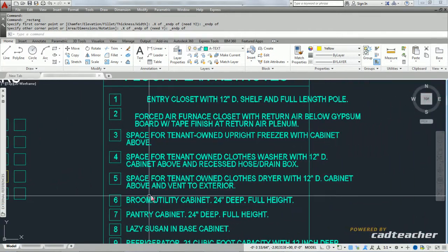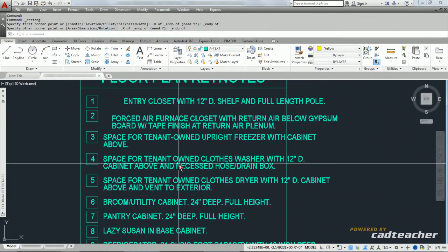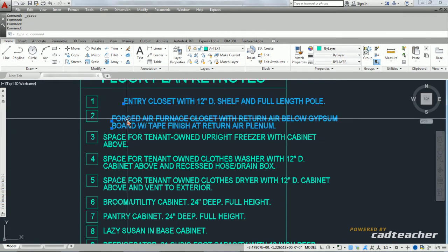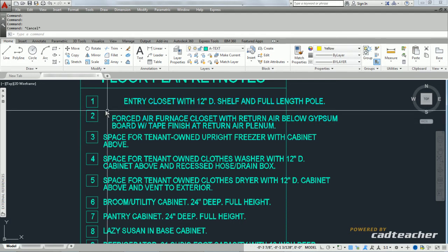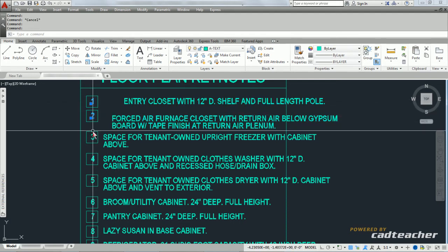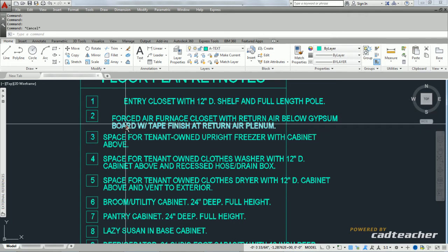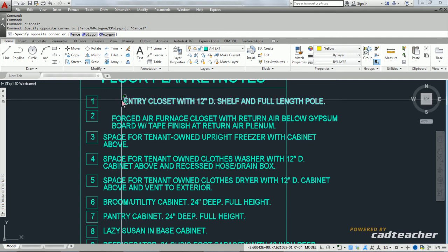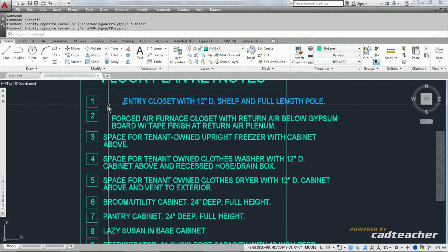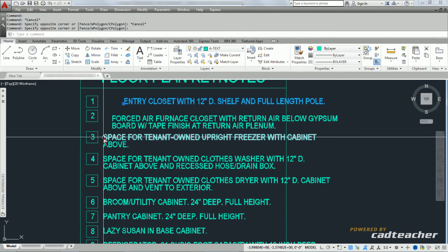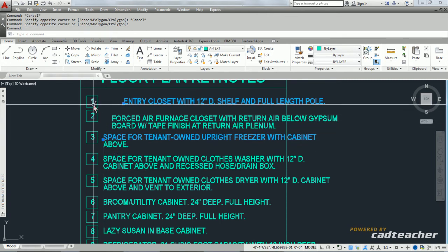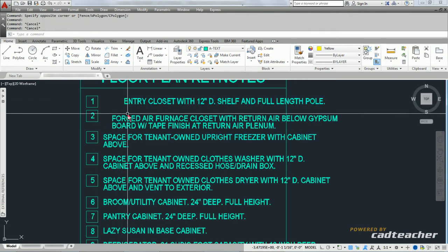Now I'd like to show you this in application. I'm just going to Control S to save my drawing. I have text here. The text has insertion points. This is independent text, which also has insertion points. What I'd like to do is reposition this text so that the insertion base point of this text lines up with the x value of the insertion base of this text and the yz of the insertion base point of there.